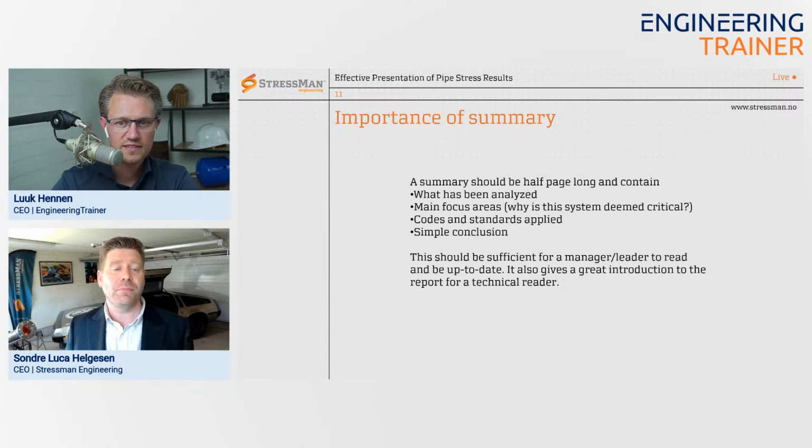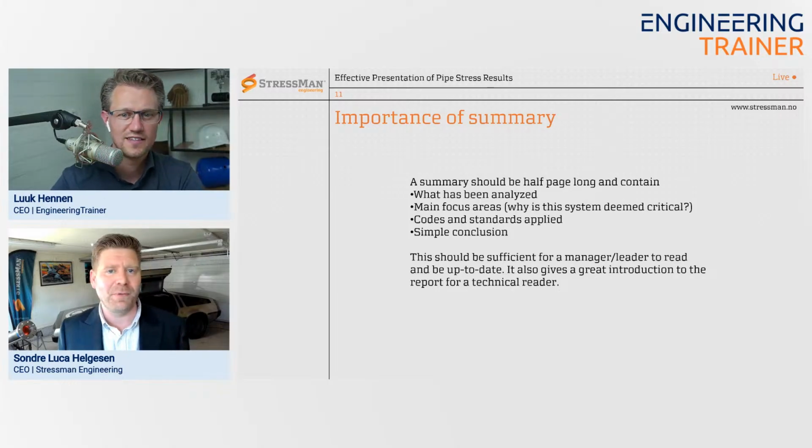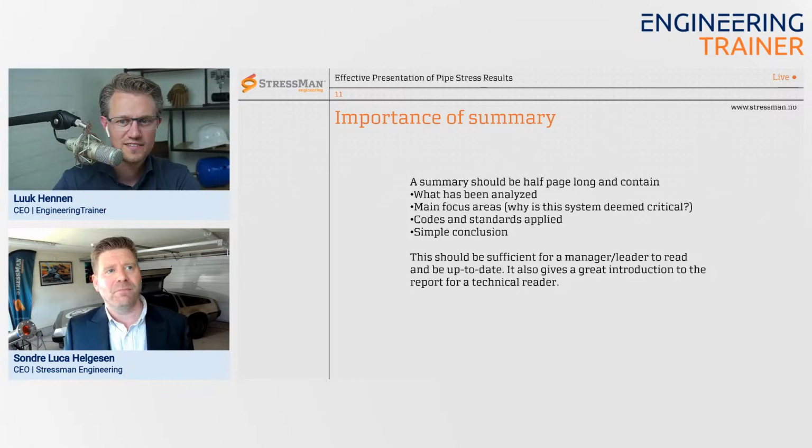Okay, we're just gonna make a small modification. That's always how it's pitched. And then you look into it, and it's like, yeah, but you're gonna put an equal T on an existing piping system, and you're gonna impose some kind of loading on the existing system. So then, how do you know that what you're doing to the existing system is okay or not? That's kind of the biggest difficulty to evaluate.